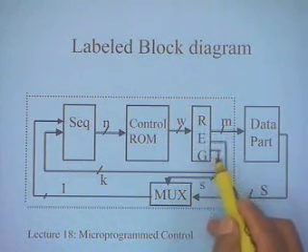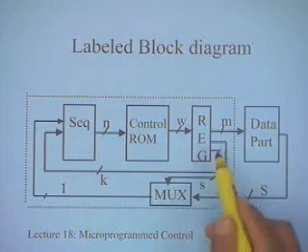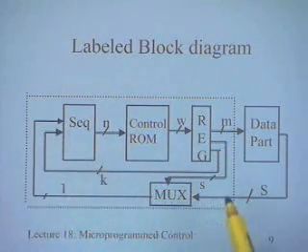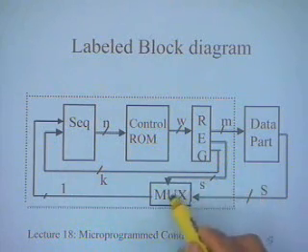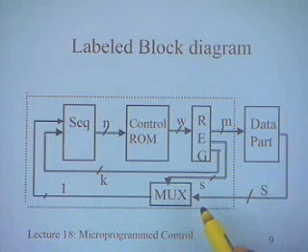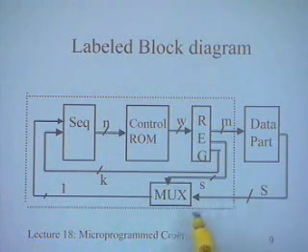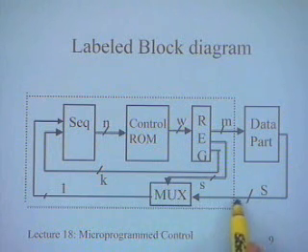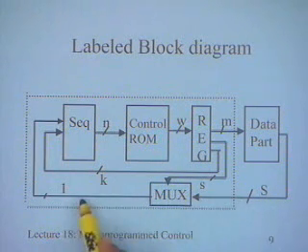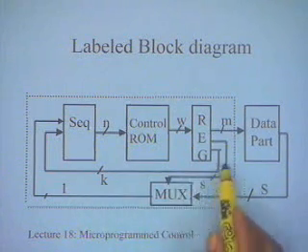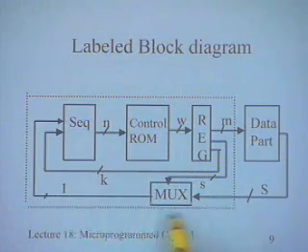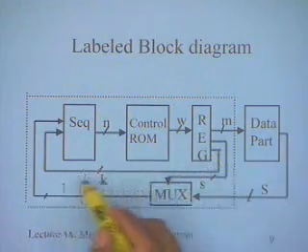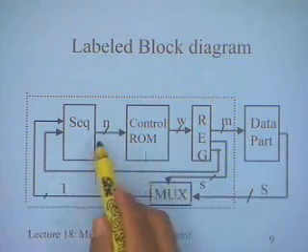So if I now look at this register output, I have some bits going into the sequencer. I have bits selecting this multiplexer input. I have to select which of the status lines I am going to consider in this particular control step, and that is being selected using this select line. So one of these lines will be selected. Remember, this has the width of 1, the rest of them are all buses. The sequencer control is going over here.